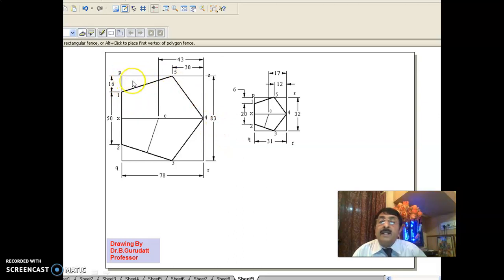And immediately enclose it in PQRS, which is the principal solid. That is a rectangular prism or a square prism. The principal solid is defined as one where all edges are isometric. They will undergo 0.816 reduction. In this way, here it is PQRS top surface, PQRS bottom surface, PP, QQ, RR, SS. They are the vertical edges, all are isometric.